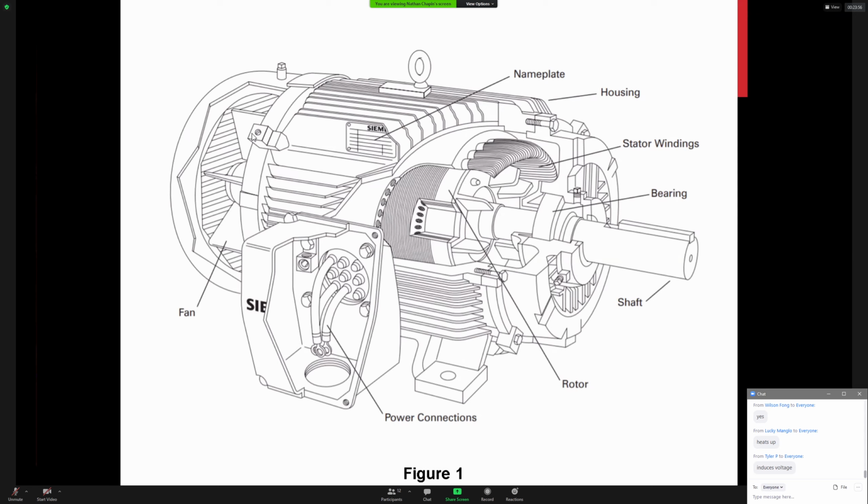So what do you guys think happens? Let's say I take this motor, which is rated at 60 Hertz, and it's a 4-pole motor. And that means it's going to turn, maybe between 1700 and 1790 RPM, which means that this fan is spinning at the same speed, cooling the motor off. If I use a variable frequency drive now to control this motor, and I run it at only 100 RPM, that means that this fan is only running at 100 RPM. So tell me this, is the fan going to be efficient at cooling this motor down?